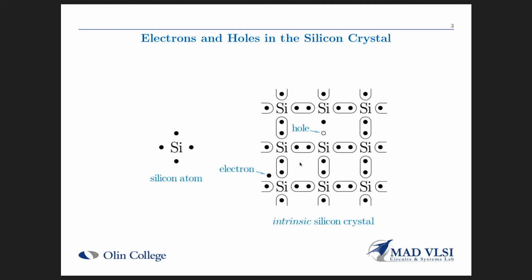And I should say that because we've invested so much in the semiconductor industry, and because silicon is the workhorse of that industry, we are able, with astonishing repeatability, to grow very large single crystal silicon crystals with astonishingly good purity, like less than parts per billion impurity levels, single crystal silicon ingots that are like a foot in diameter and like 6 feet tall.